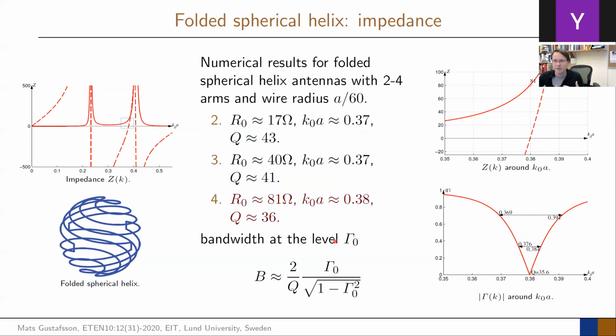And you can see the same feature again. So here we see similar things, the radiation resistance, electrical size of it, it changed a little bit. The Q went down a little bit, but not much. It just shrank a little bit. And mainly here, the radiation resistance now increased again when you went up to this. And now it's like above 50.